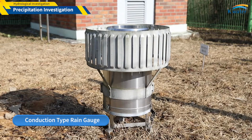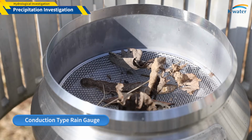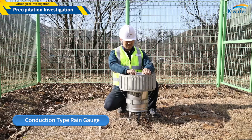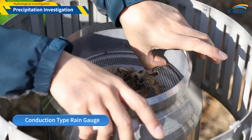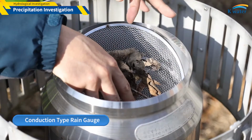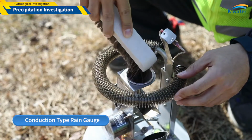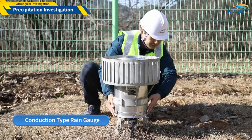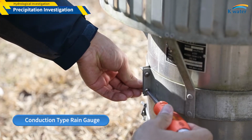The water inlet of the rain gauge must be positioned horizontally at least 30 centimeters or higher from the ground level. Check the water inlet of the conduction-type rain gauge for internal damage, deformation, rust, etc., and check the mesh regularly to ensure no problem with the measurement of precipitation. Be careful not to damage the rain gauge when cleaning, and check the drainage hole clogging, horizontal position, and screw loosening.